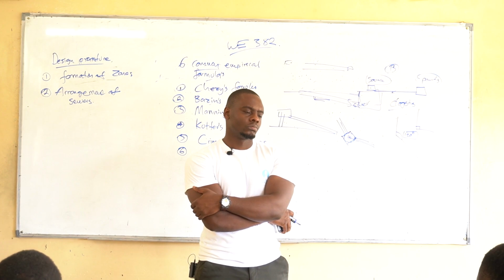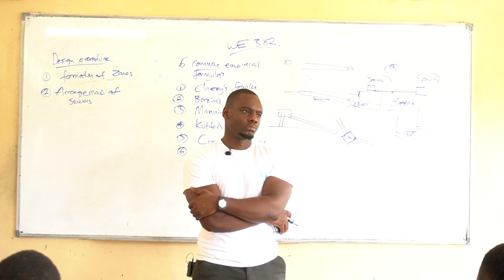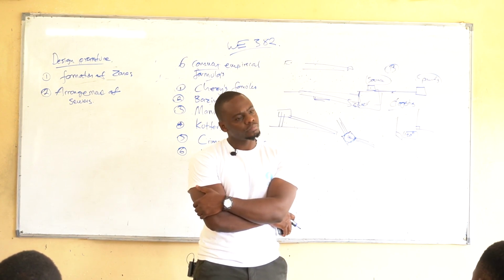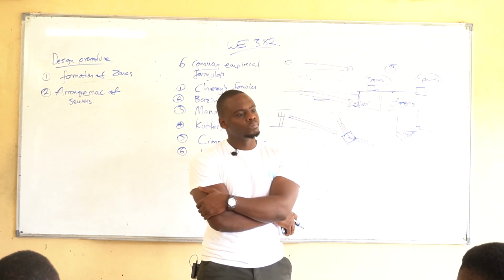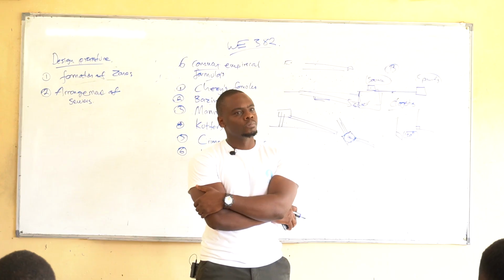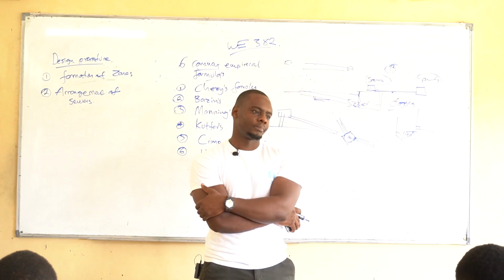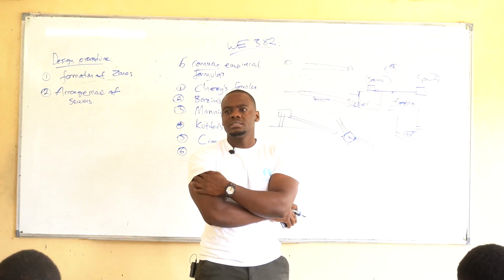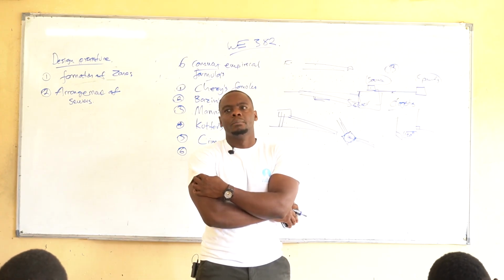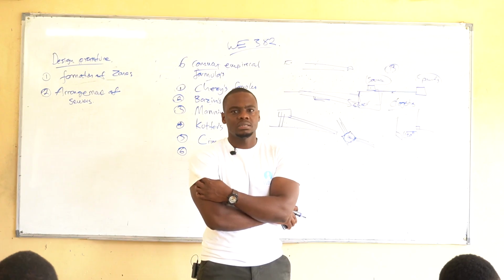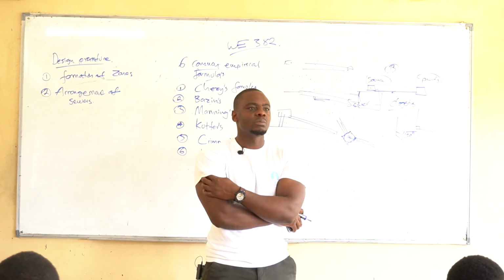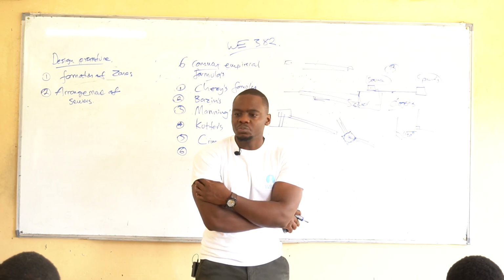So you find that maybe you want to design a sewer network system, and there is also a water network system. So provided there's a lot of congestion, is it okay to have them run together? No. So you always make sure they are apart by meters, because you're always anticipating, like I said, as engineers, we're always looking for problems. What could arise from this problem?